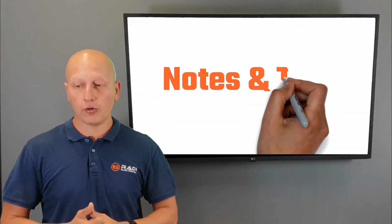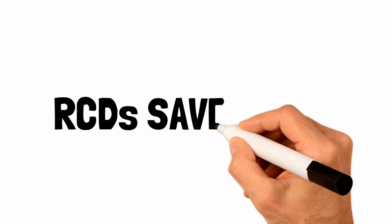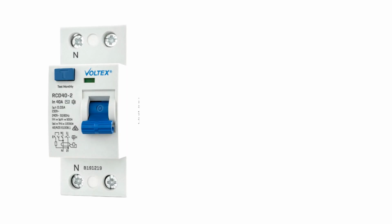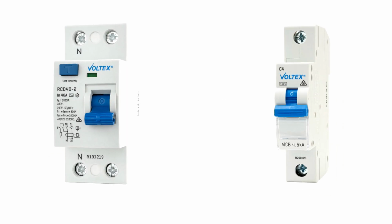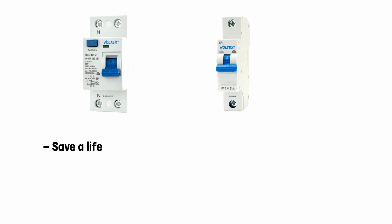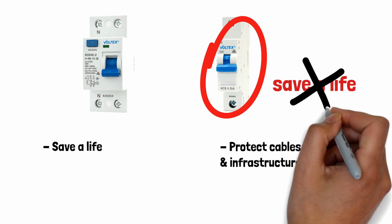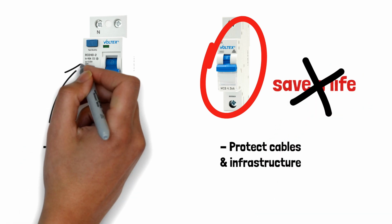So let's conclude it all. Firstly, RCDs are designed to save lives. Always remember that when dealing with RCDs, there is a difference between an RCD and a circuit breaker. A circuit breaker protects the cables and electrical infrastructure, but it will not protect life in most situations. An RCD is designed to save lives.